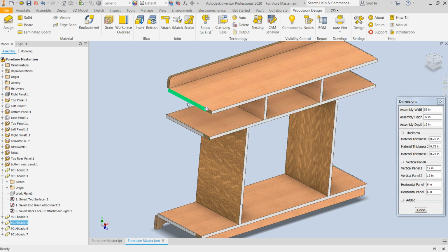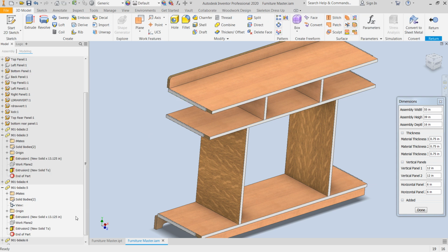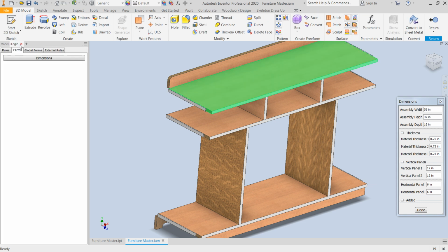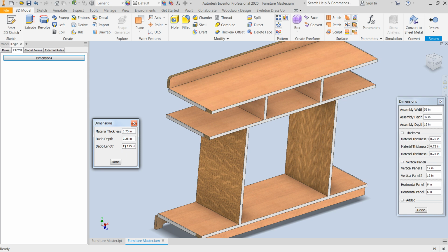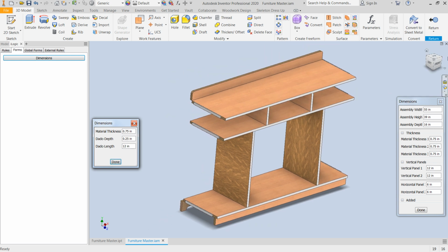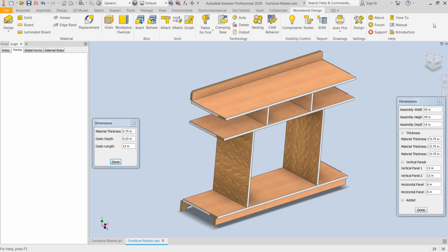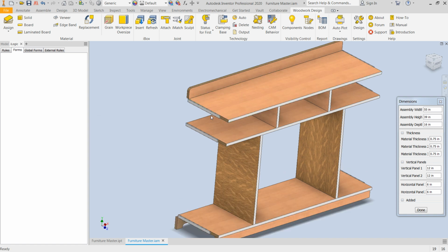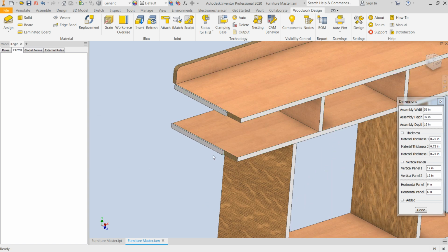So in other words, if I click on any of these right now, and I go ahead into iLogic and I say I want to change the dimension, let's make the dimension 12 inches deep, not 13, and hit return, they're all now 12 inches long and leaving me with a much deeper dado or blind. But that's up to you. Change the depth, how far into the panel, all those things are adjustable. Or if there's other things that you need adjustable, you can, of course, handle that.